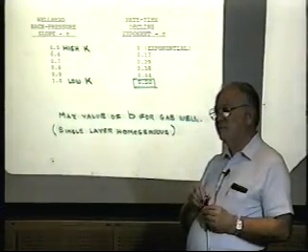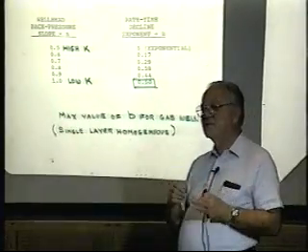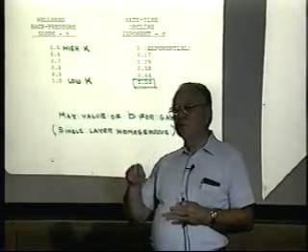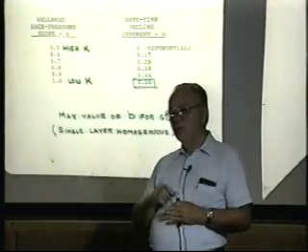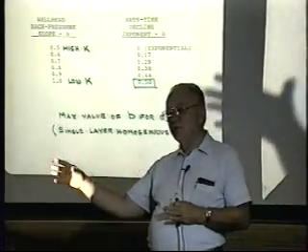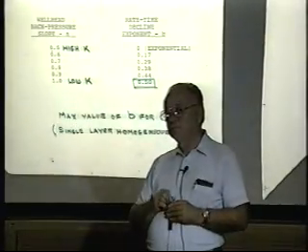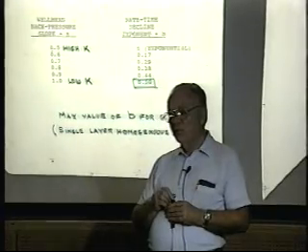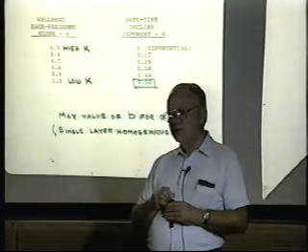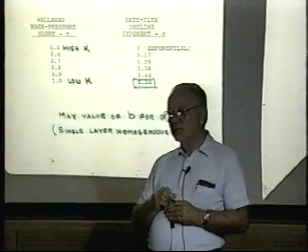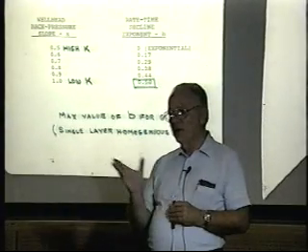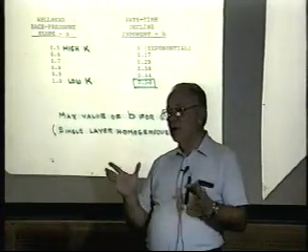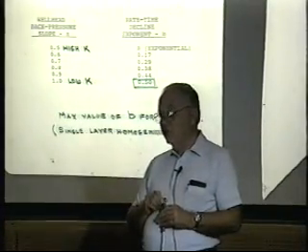So it's not accurate. And it's a competitive situation. This is the other thing you have to keep in mind. If you don't produce those reserves, and the offset operator understands this, he's going to produce your reserves. Every well drains a volume in proportion to its producing rate, even by layers. So if the other guy stimulates and you don't, he's getting your reserves and your early production. It's not just deferred. It's lost forever.